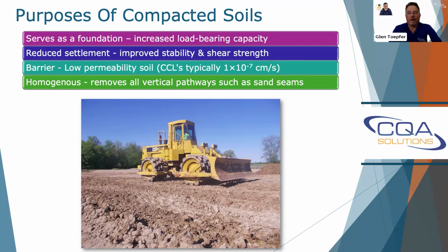The compacted clay liners, low permeability soils, and most of those you want fairly homogeneous to alleviate vertical pathways such as sand seams or anything that could bring water or other things up into your compacted soil and cause it to fail over time.